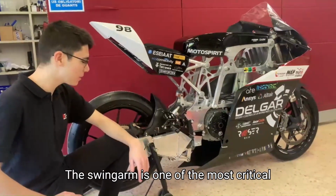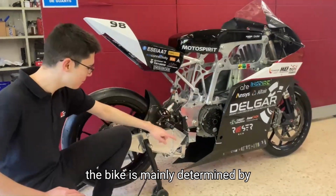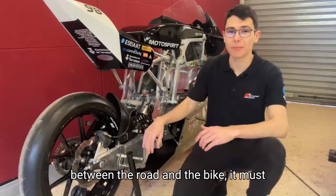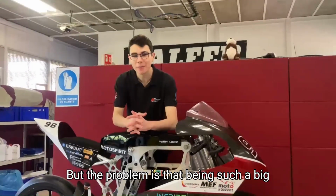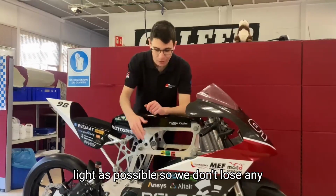The swingarm is one of the most critical parts for us. In fact, the behavior of the bike is mainly determined by its geometry. And of course, since it is the connection between the road and the bike, it must withstand great forces and momentums. But the problem is that being such a big component, it is crucial to make it as light as possible, so we don't lose any time on track.